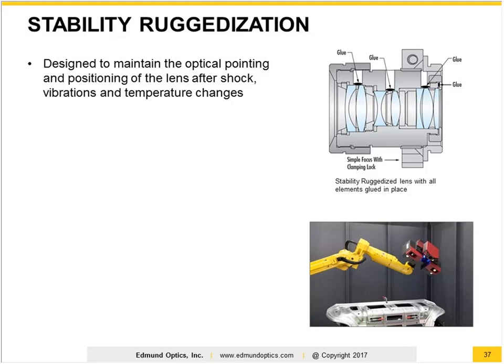When the lenses are assembled together and locked down and put into place, the optics are in one position. If they're put into a system and calibrated, they're probably still pretty close to that position. But as you have wild temperature changes, the aluminum or other metal materials holding the optics in place change in size and dimension, and the optics have the opportunity to shift around. That leads to a lack of pointing accuracy. When we think back to the pixel sizes on the sensors, and we're trying to hold 1 or 2 microns of shift, that can be enormous for the beam pointing. We're going to see more about that in the final slides of the presentation, but temperature can come into play and become a real issue.